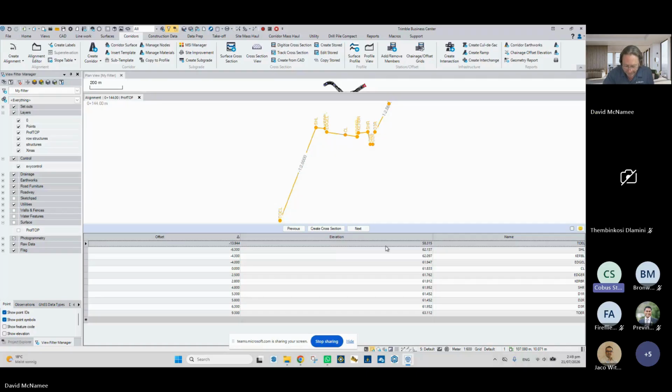Is there any way that you can do as-built on the existing road and pull them into TBC to check the IRIs? Yes, you can go off with a scanner. You've got a Trimble SX12 scanner, you can scan the surface. You've got a mobile mapping scanner, you can scan the surface, or third party, whatever it is. If you're doing asphalt or concrete paving, it saves .pav files.